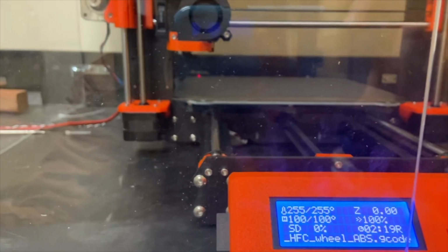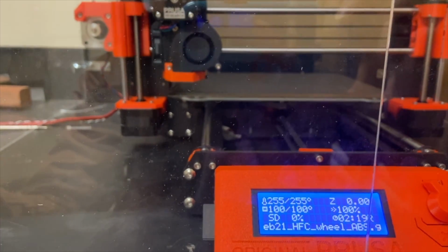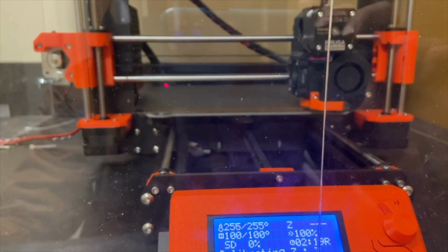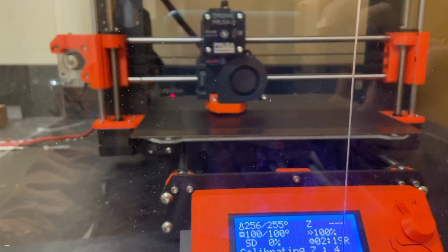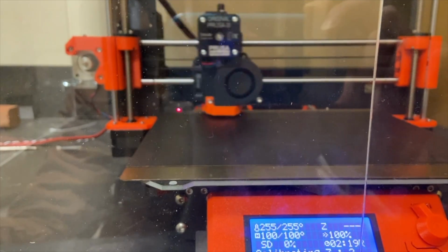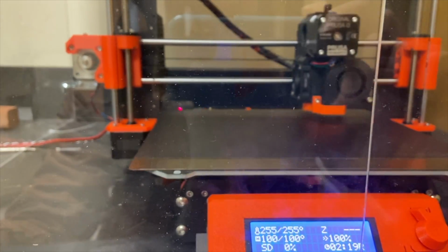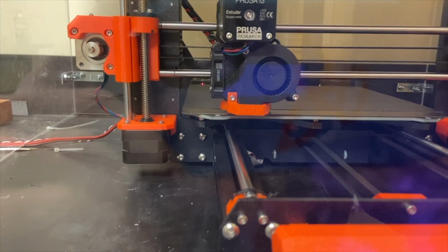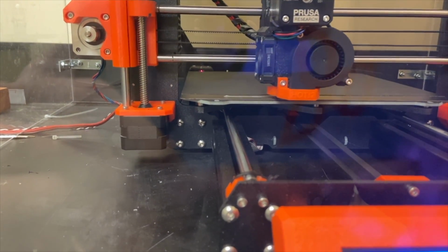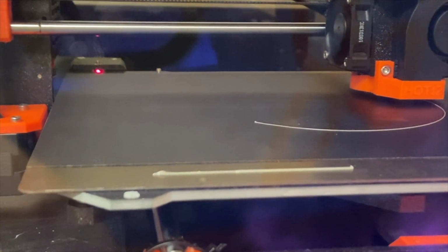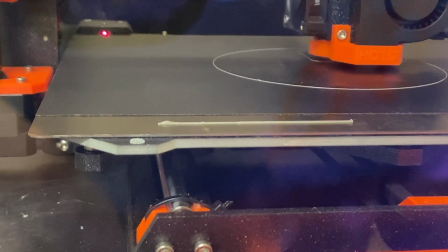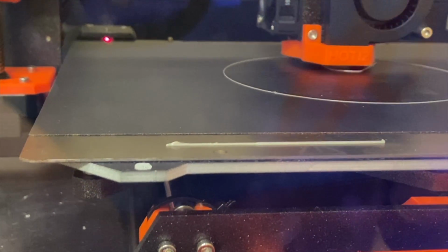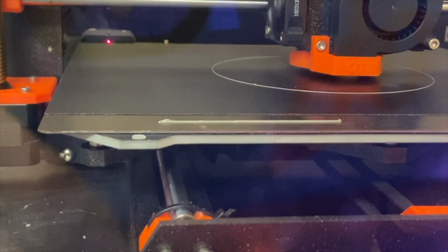This is not a comprehensive calibration. It will do this at the beginning of every print, just identifying the boundaries of the print bed and midpoints. And then it will print a test. There's a little bead at the beginning. And if this goes well, then I think I should be good to go and come back in 2.5 hours.